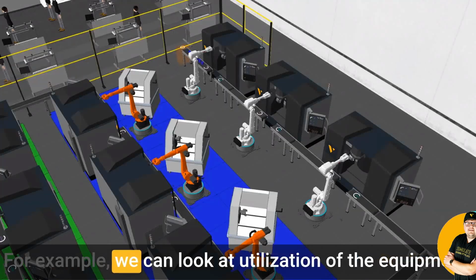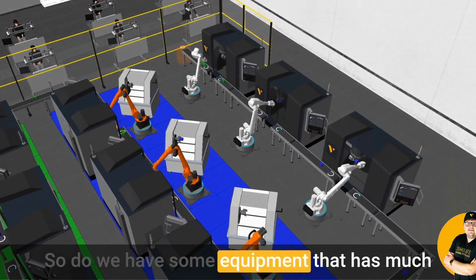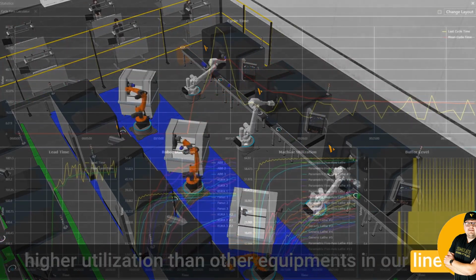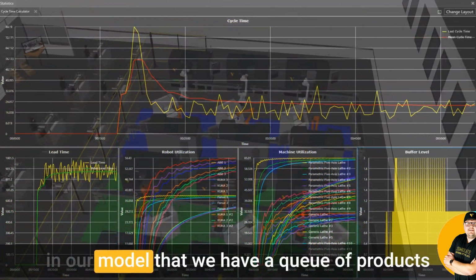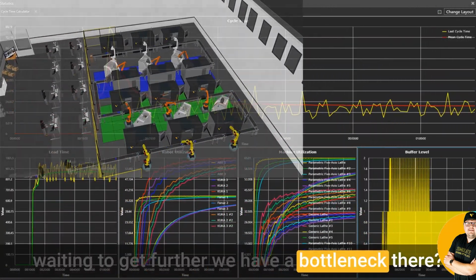To find out where we have the bottleneck, we can look at many things. For example, we can look at utilization of the equipment. Do we have some equipment that has much higher utilization than other equipment in our line? Then likely we can have a bottleneck there. Do we have places where we can see visually in our model that we have a queue of products waiting to get further? We have a bottleneck there.